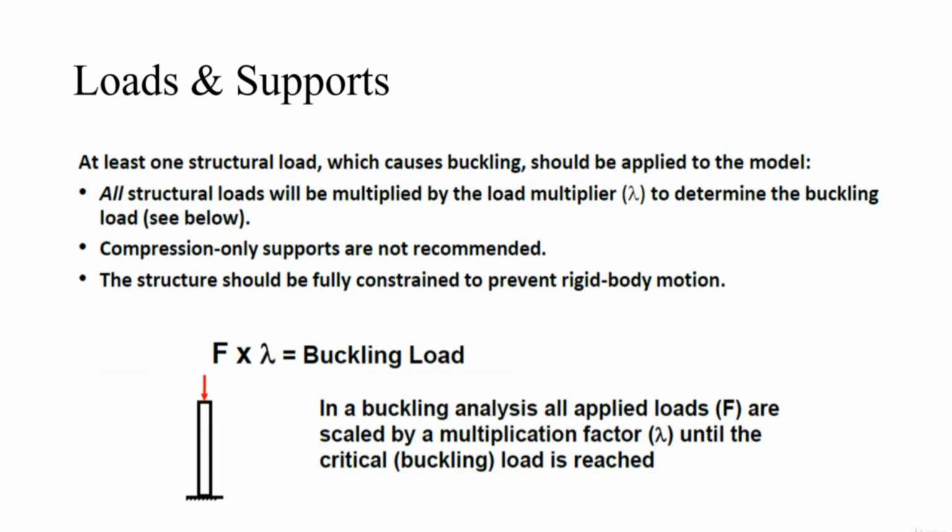Then coming to the loads and supports, all types of structural loads can be applied on these bodies in order to perform a buckling analysis. Compression only supports are not recommended in this particular type of analysis. The structure should be fully constrained to prevent rigid body motion and in order to get good results.